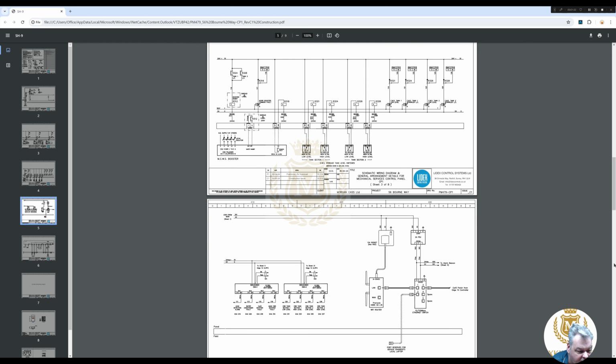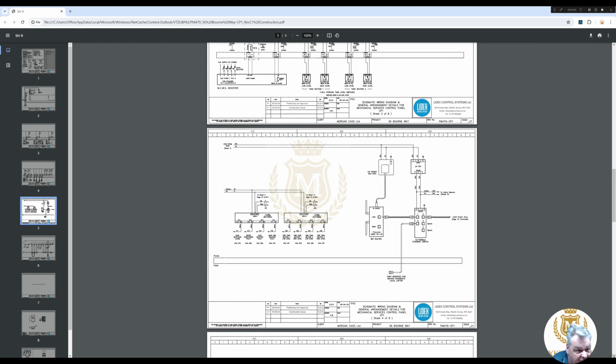What else have we got? We've got two DIM units here, the DIM 4s, DIM 41, DIM 42. So there are your inputs going into your units, and coming out we've got a 0 to 10 volts, so we've got to put that in there. We've got a Wi-Fi router going in there for remote connection. They've given a 24 volts DC power supply here for the Ethernet switch. So we've got two DIMs going in,